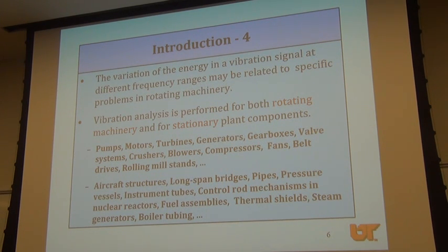Then it talks about the variation of the energy in the vibration signal at different frequency ranges, which may be related to specific problems. When a machine operates, there may be different frequencies because of various types of anomalies or faults. If I can measure these frequency components, I may be able to identify what is causing this frequency change, what is causing the other frequency change, and so forth. So I may be able to detect the fault or diagnose the fault.